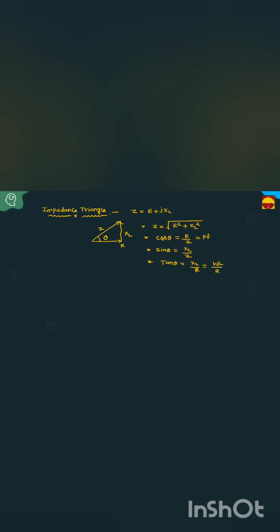In a series RL circuit, tan theta equals XL by R, and from this we calculate theta: tan inverse of XL by R. Wherever the RL circuit is there, how to calculate the angle? Tan inverse XL by R. Clear? From this, what is R? R equals modulus of Z cos theta. I gave this formula at the start. What is XL? Modulus of Z sin theta. XL is the inductive reactance, equal to omega L.